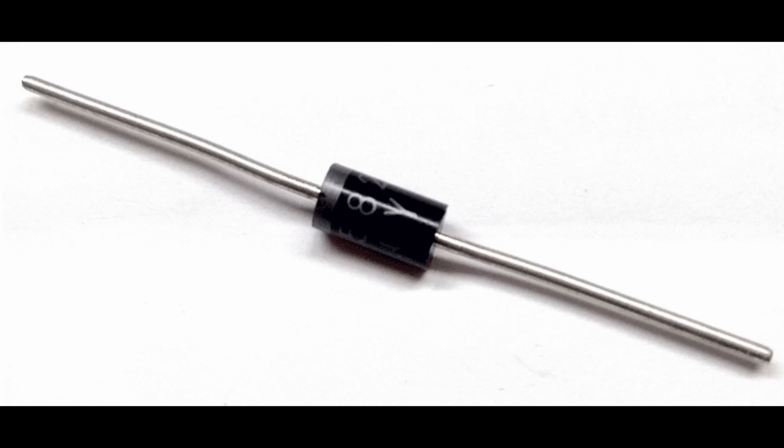Due to their low carrier storage time, Schottky diodes have fast switching characteristics. They are widely used in high-frequency rectification and fast switching circuits. In general, fast switching speed means that the device can change its operation state rapidly, typically within nanoseconds to microseconds, depending on the specific component and application. This capability is crucial in various electronic circuits and systems, especially those involved in high-frequency applications and fast digital signal processing.